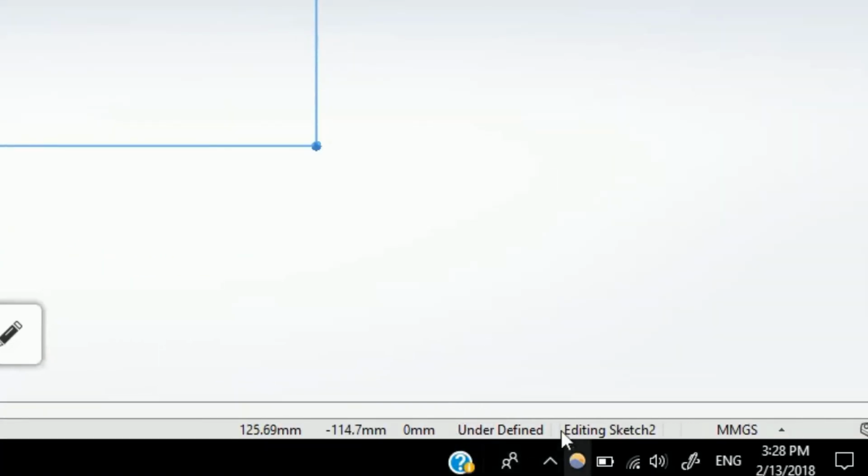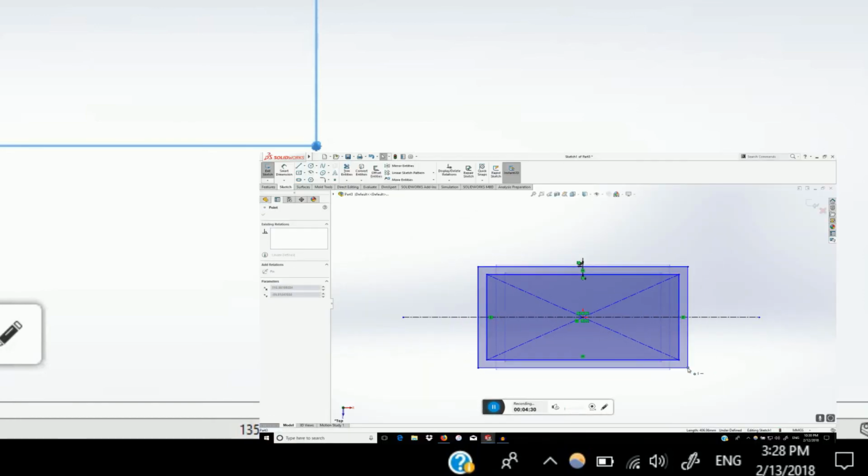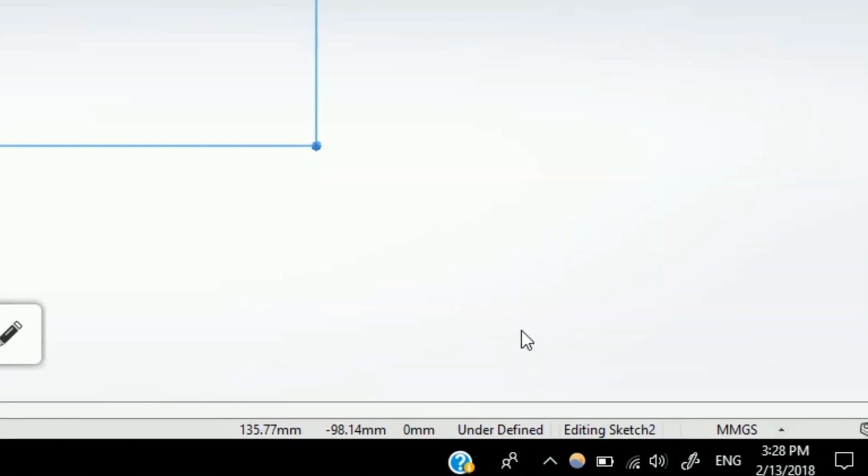Concerning the fully defined remark I made earlier, you will see a comment from SolidWorks about the current sketch. Defined in this context means whether all your sketch features are dimensioned and fixed. Underdefined features will be blue in the sketch, which means they are not defined by a dimension and you can drag them with the mouse. Fixed elements are black. In engineering applications, it is important, or at least desired, that all sketches are fully defined.